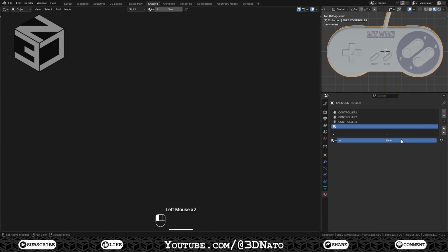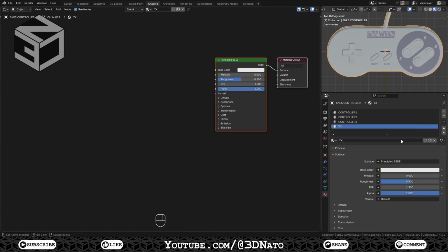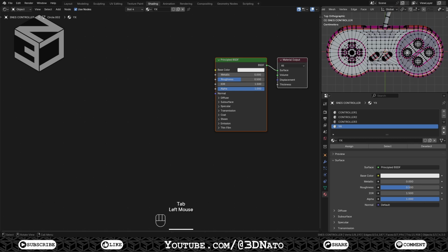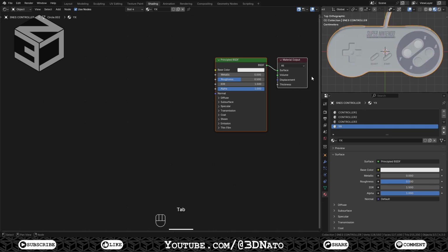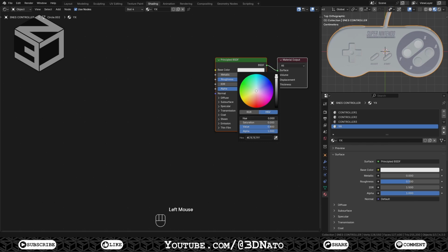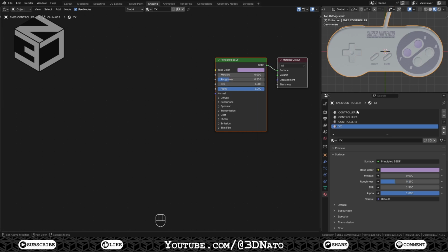Press the plus sign to add a new material and rename it YX. Go to Edit Mode, select both Y and X button faces, click Assign, and exit Edit Mode. Set HSV hue to 0.75, saturation to 0.5, and value to 0.5 to make a light purple color, and set roughness to 0.25 to make it shinier.